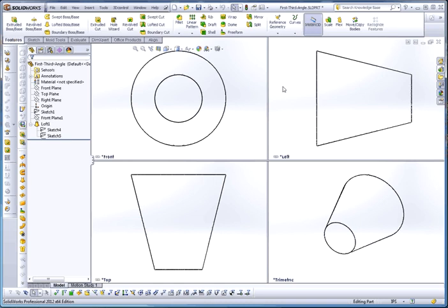The fold lines are the same. If you think about this being a fold line between the front view and what's going to be the left view, what you're going to do is fold this up, and that makes this consistent with the left view. It's just that that left view is not on the left of the front view, it's going to be on the right. Think about this as being your fold line for the first angle projection. Instead of folding that down like we did in the third angle, this gets folded up. So now that becomes consistent with the top view.